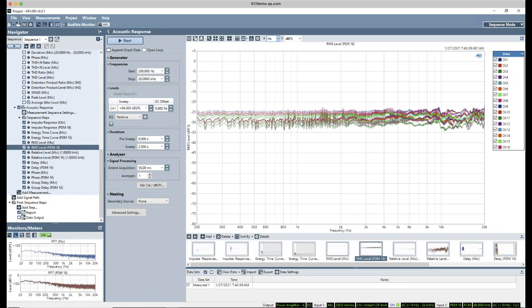But let's just set this aside for a moment and say, well, I'm generating 94 dBSPL, 1 Pascal. So the sensitivity of mic 1 is, well, just about minus 25 dBFS per Pascal. There are additional little things I could do here.